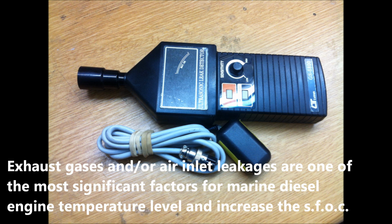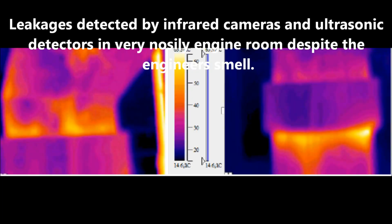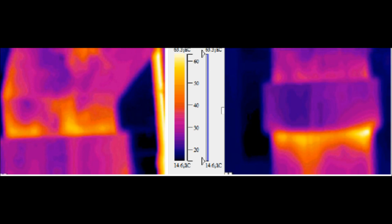Exhaust gas and/or air inlet leakages are one of the most significant factors for marine diesel engine temperature level, and increase the specific fuel oil consumption. Leakages are detected by infrared cameras and ultrasonic detectors in a very noisy engine room, despite the engineer's sense of smell.